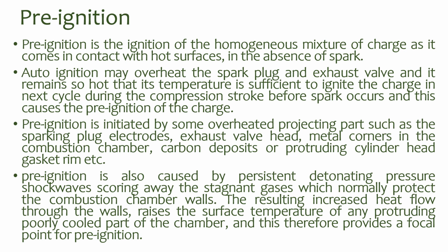Pre-ignition is initiated by some overheated projecting part such as the spark plug electrodes, exhaust valve head, metal corners in the combustion chamber, carbon deposits or a protruding cylinder head gasket rim, etc.